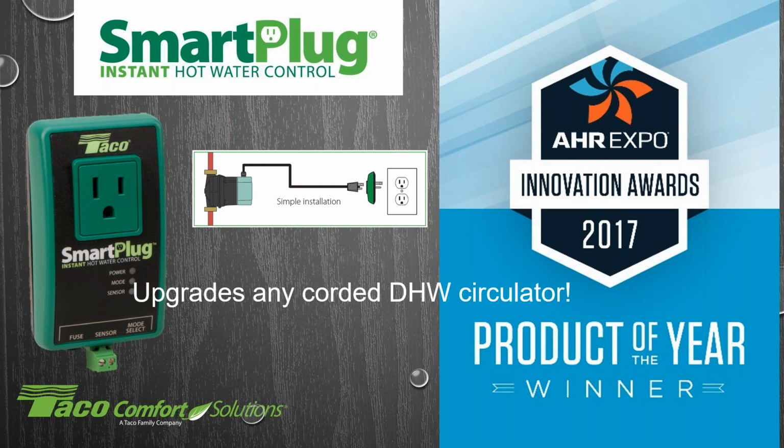The following Sunday, I'm going to make sure my circulator turns on a little bit before that 5 o'clock and a little bit after that 5 o'clock to give you that window of opportunity to get into the shower itself and run the circulator for those time periods. So when you first install the smart plug, it runs for 5 minutes on, 10 minutes off for the first 7 days, looking for those events.